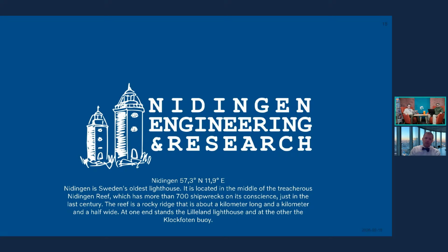I use the simpler model, and I compensate for the lack of detail with huge sensitivity studies and design of experiment matrices. I could have added more detail and gotten closer, but because I have uncertainty in my model, since it's simple, I run it multiple times, varying different inputs. Then I can easily see, and get a mathematical statistical proof, that my system will behave within the bounds I want.